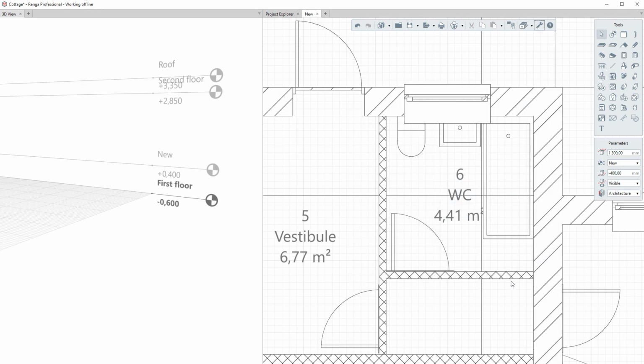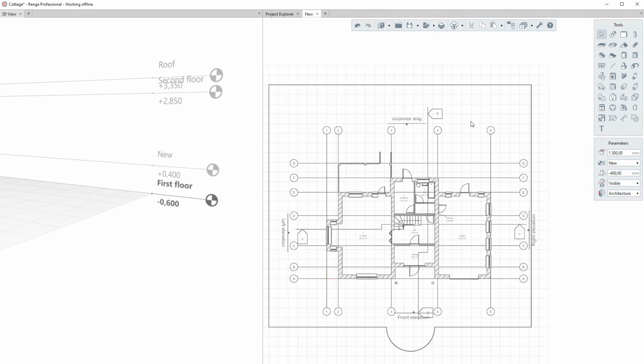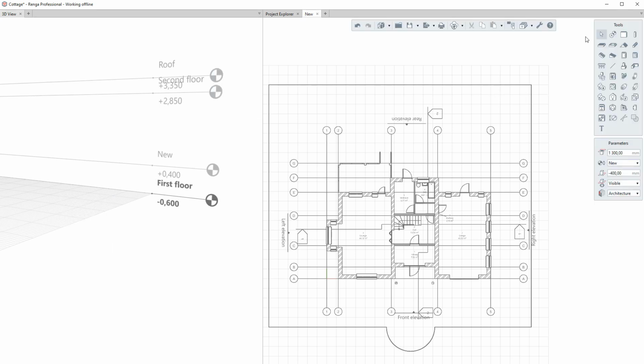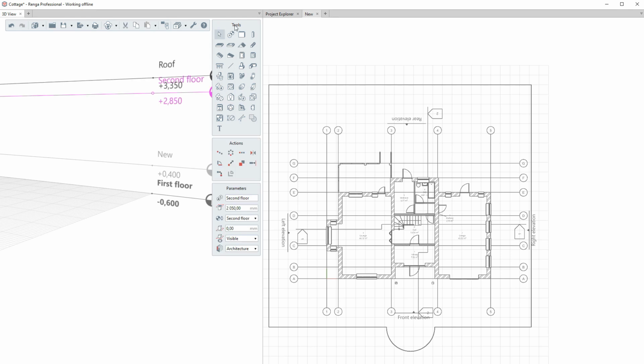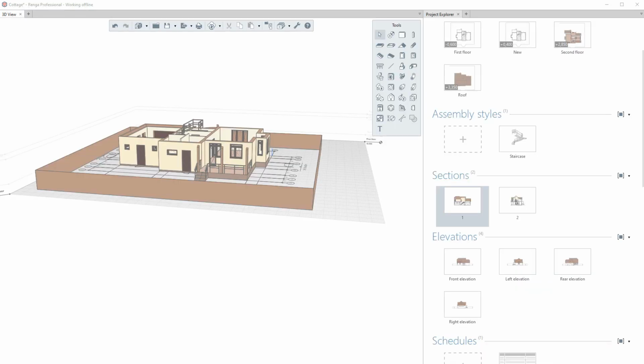The principles of work with tools are the same on both 3D and 2D views, but the cubic, cylindrical and spherical measure modes work only in 3D view. If one of these measure modes is required to build an object, go to 3D view. All tools and actions on the right panel are available on 2D view as well as on 3D view. To make your work with level plans convenient, you may specify the level's plan parameters on the Tools panel. The next project component is sections.